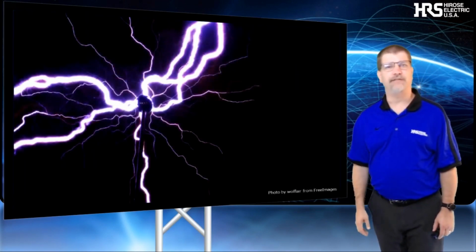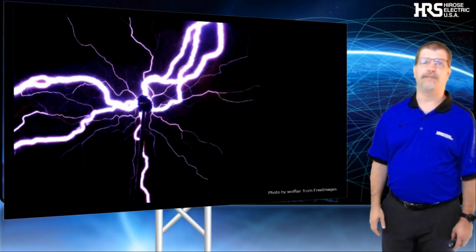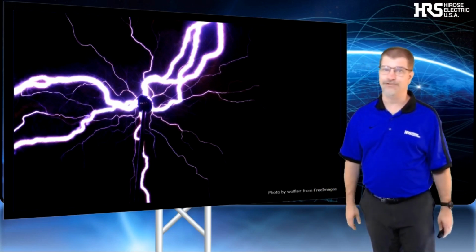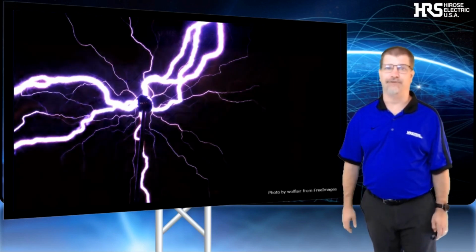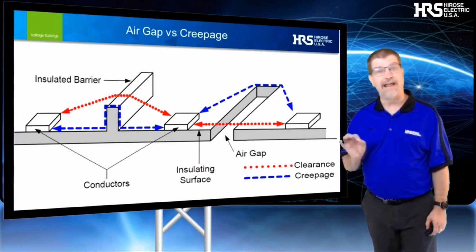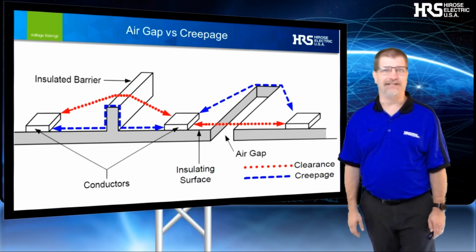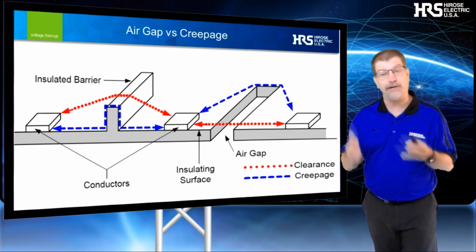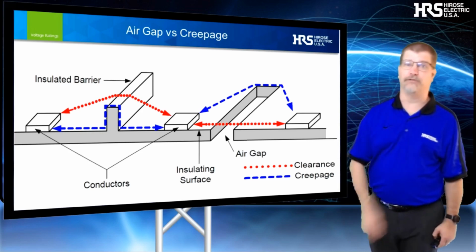Now let's talk about a few of the other design considerations, starting with the voltage. Voltage ratings seldom come up as an issue on power connectors, since typically when the voltage gets higher, the current ratings are also higher, resulting in a physically bigger connector, and hence a higher voltage rating. The two key values in a power connector when determining voltage are the air gap between the contacts and the creepage distance. We like to ask what the voltage is and make sure it is within the ratings of the existing target family that we've been working with you on based on the previous current discussion. Honestly, I seldom have issues here, especially with the Hirose connectors.